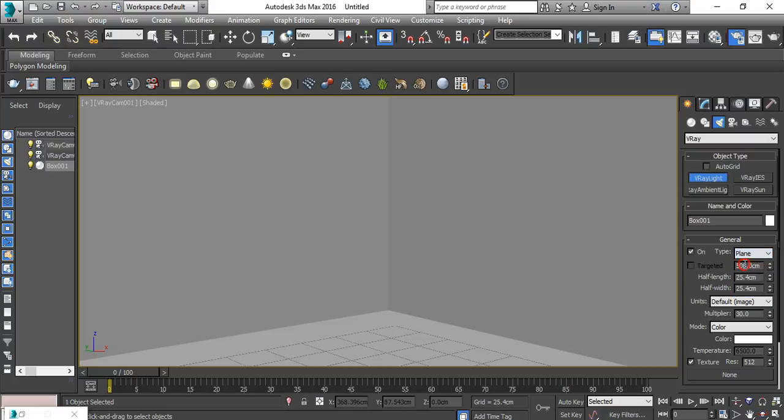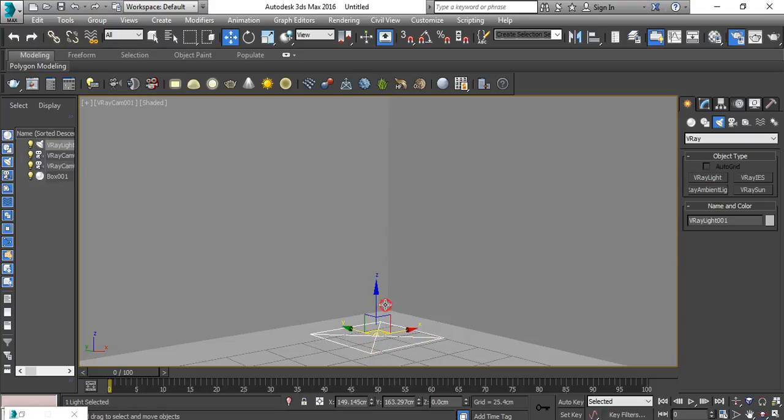So the plane, what is the plane? You just have to click here. In the V-Ray light, default plane is selected. You have to draw this plane somewhere. Okay, let me take it up, and you see we have a light here. This is a V-Ray plane light. You can see the arrow is in the down direction. Okay, that means it's pointing down. That means the light is coming down.